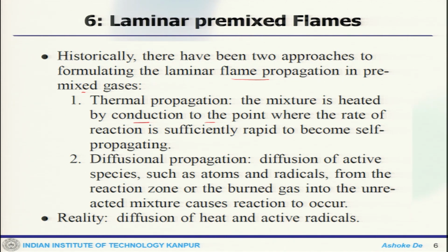So, that is a concept completely based on thermal analogy, and the second one is based on diffusional propagation, which talks about diffusion of active species such as atoms and radicals from the reaction zone or the burned gas into the unreacted mixture, which causes reaction to occur. So, there are two completely different thought processes.